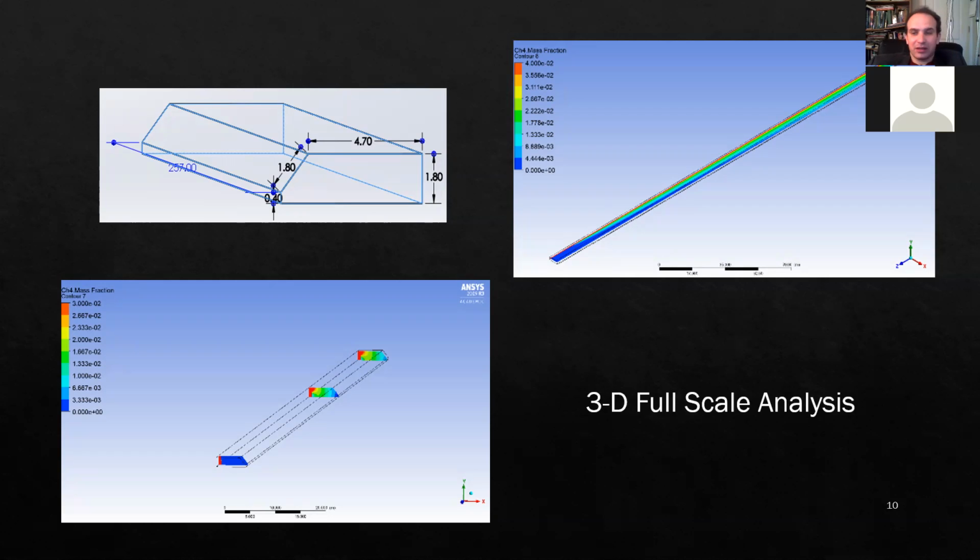Yeah, no. Like I said, I haven't gone in and self-defined anything other than simply turning on those species and defining exactly where they are, where they enter from. So like I said, the air is entering from here. I have this whole face right here defined as just an O2 or an air inlet. And then as it proceeds through, it's picking up the methane from the wall here. I haven't gone in and changed anything really specifically.